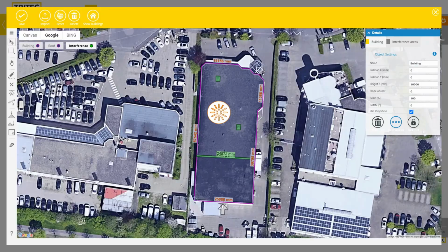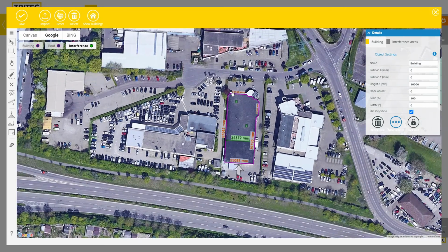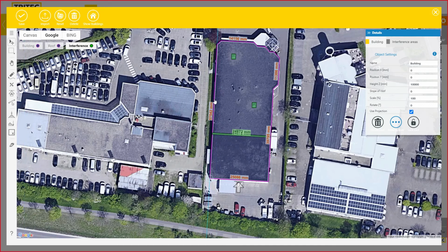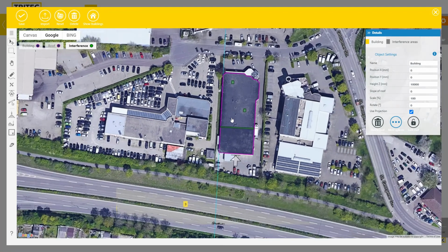And you see now here, this is a building where you have an irregular roof outline, and very easy. You see the guidelines are not saved, but there is snapping to the existing outline, and then I could really easily draw these. And here I just release to draw this. I'm just releasing my shift key on my keyboard up to this point, and then press it again to be sure that this line is parallel to my guideline. It's very, very easy to use.